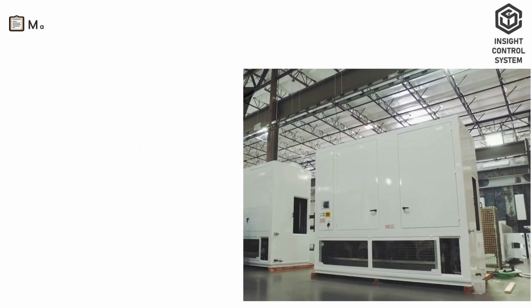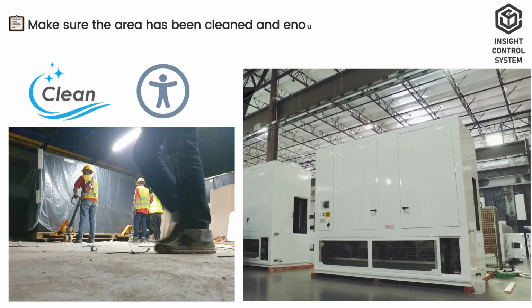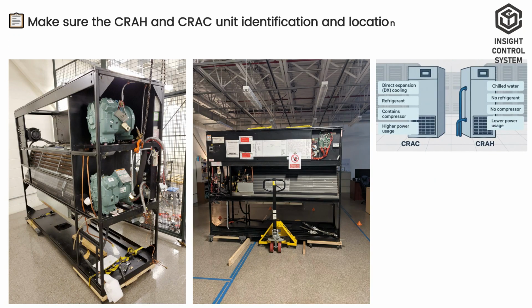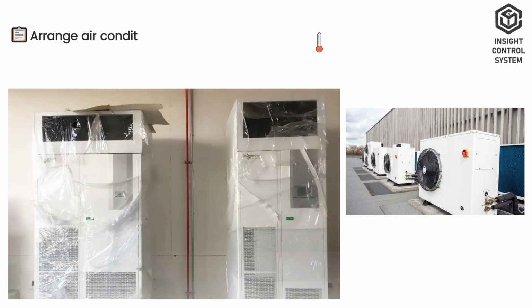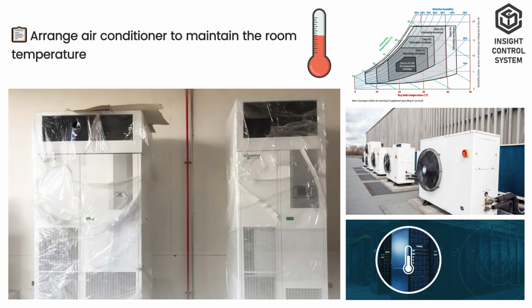Pre-installation check. Make sure the area has been cleaned and there is enough access to install the CRAC unit. Make sure the CRAC unit identification and location are as per drawing before installation. Arrange air conditioning to maintain the room temperature as per specifications.